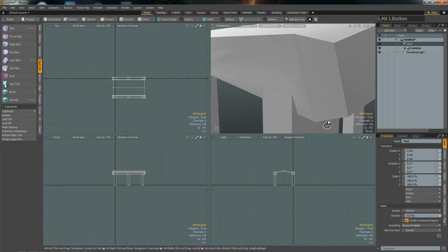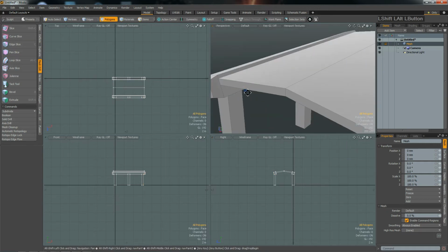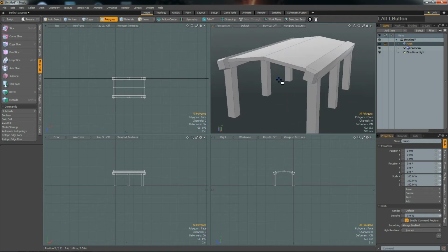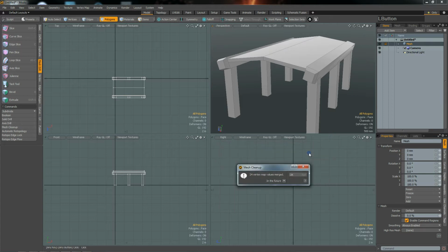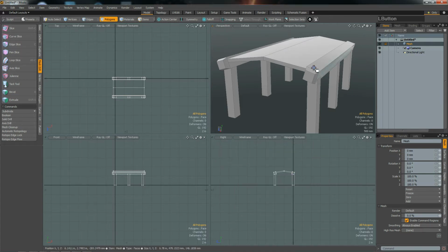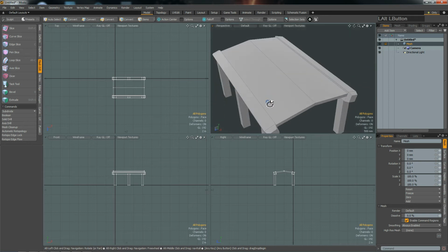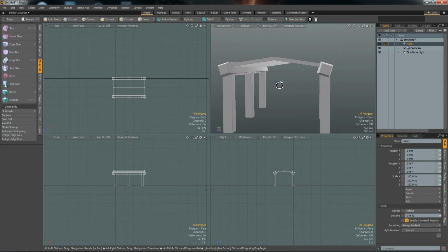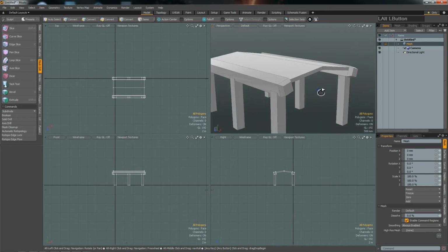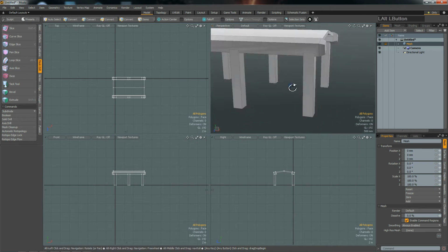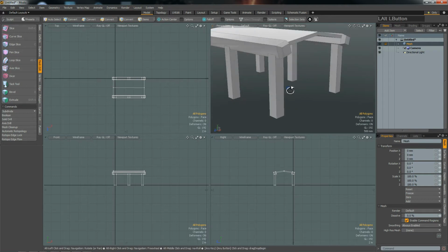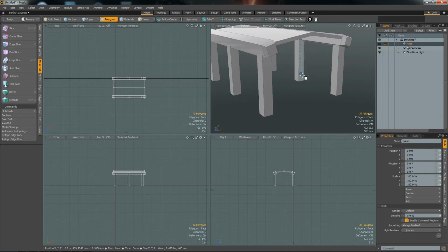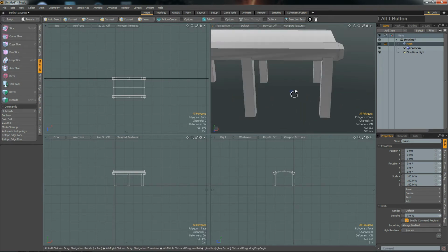And yeah, it just works without any further correction, except we do the obligatory mesh cleanup after such a Boolean operation, and again it cleaned up some of the vertices. And now we're creating some walls, or one wall segment that we can use then over on the other sides, and one front and one back wall segment.